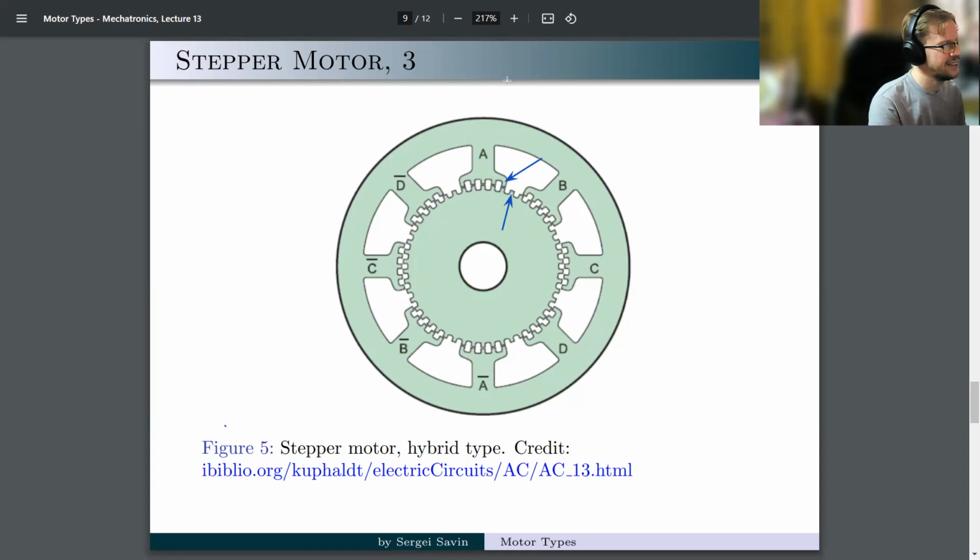Now, they are slightly misaligned. As you can see, these teeth here align perfectly with the teeth here, right? There's a perfect alignment. While here, there's clearly a misalignment. And here the teeth misalign so much that they look at the gaps instead of the teeth. So if we had a continuous ring of teeth on the stator, there are fewer teeth on the stator than there are on the rotor. This is made on purpose unsymmetrical in the number of teeth.